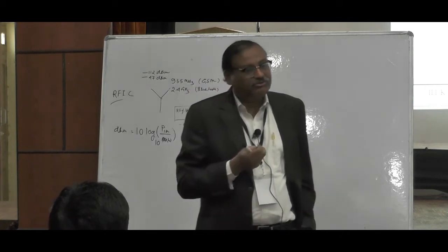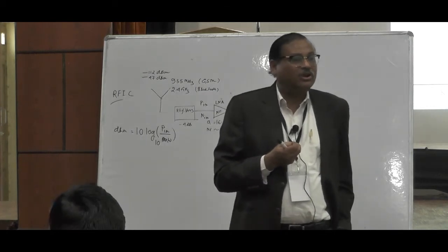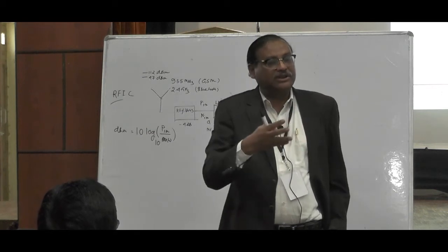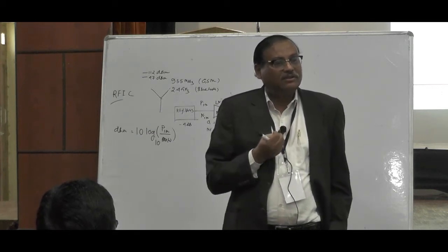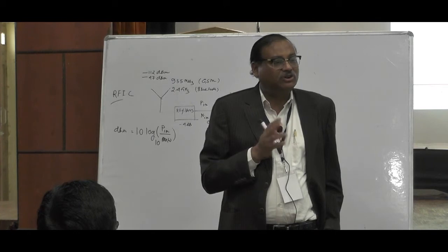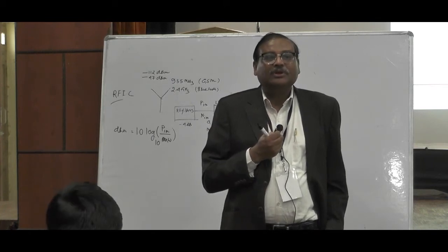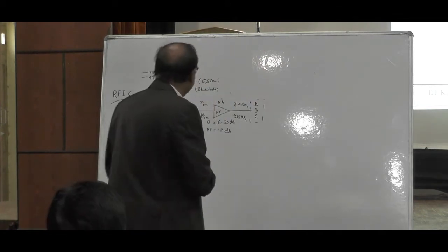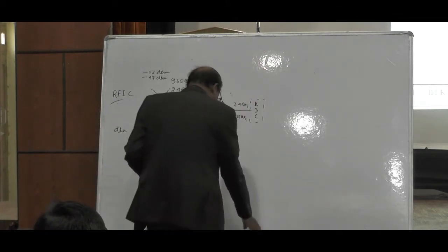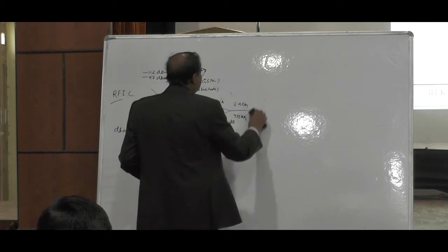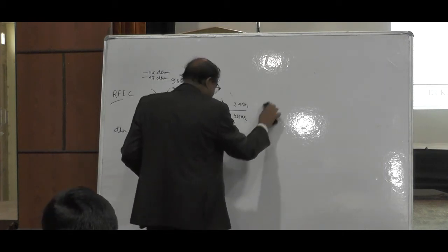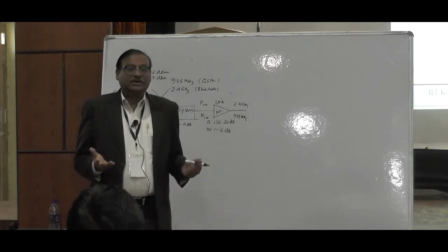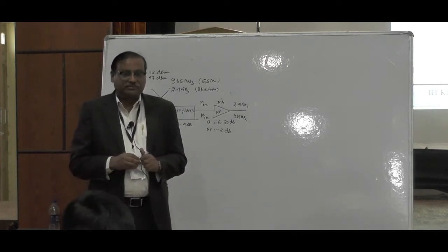So that kind of software radio, which you call software defined radio, where just after the antenna you need a low noise amplifier and then put an A to D converter, is not possible. Then what next? All of you know that we talked about the heterodyne or super heterodyne kind of receiver, where you need some kind of frequency down converter.